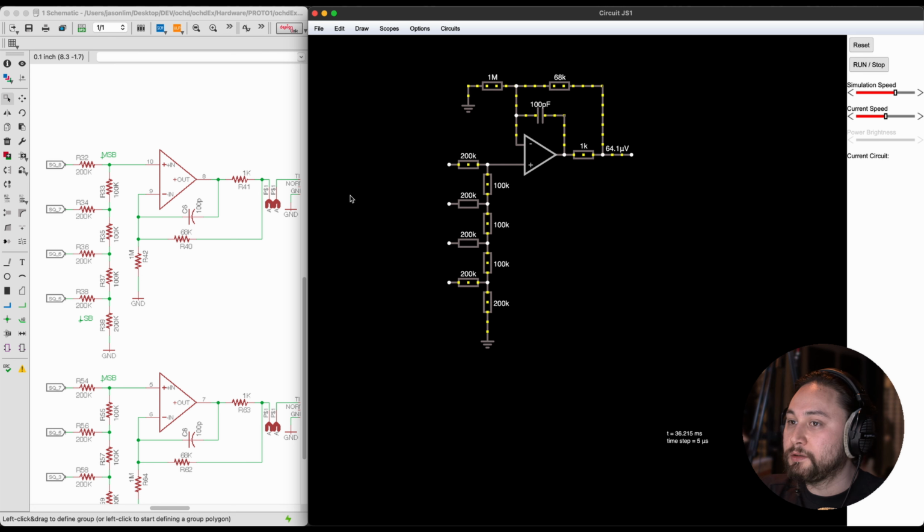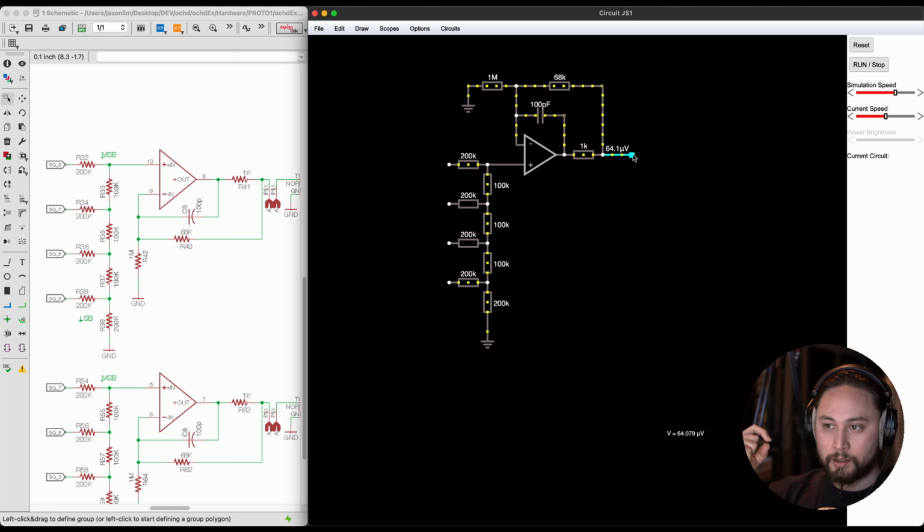Let me show the voltage here. What we need to do is apply a combination of high and low bits to each of these states. So this is digital to analog. Digital signals being high or low, 0 to 5, and analog being our variable voltage, which in this case is going to be 0 to 5 volts with 16 discrete voltage steps, and that comes through there being 16 discrete combinations of 1s and 0s when it's working in 4-bit logic.